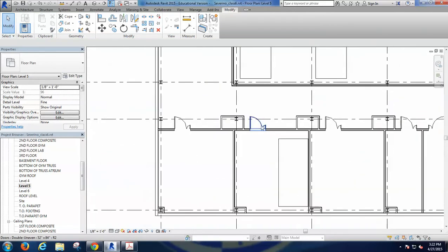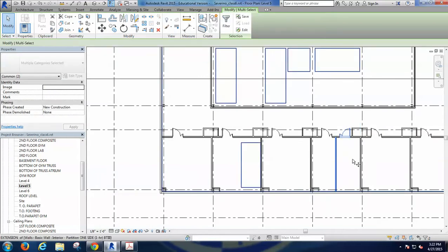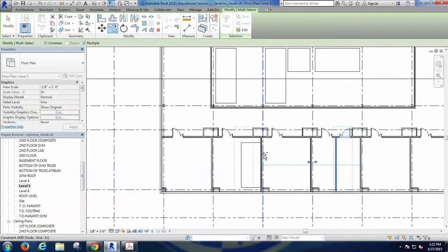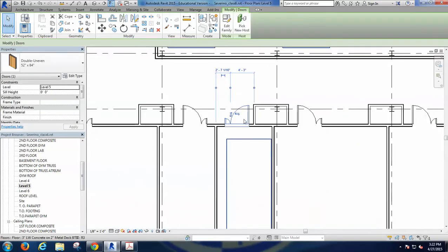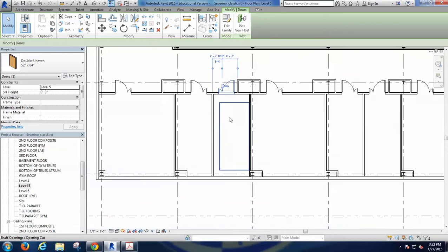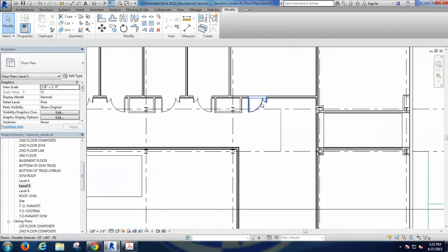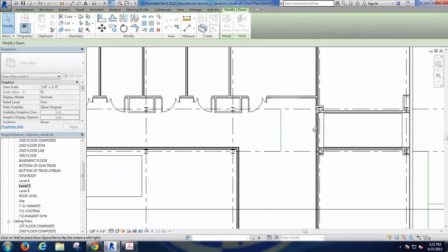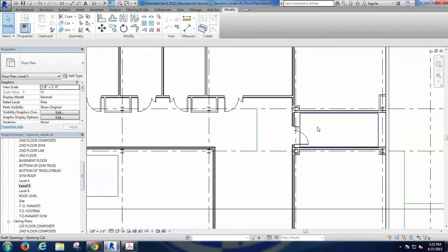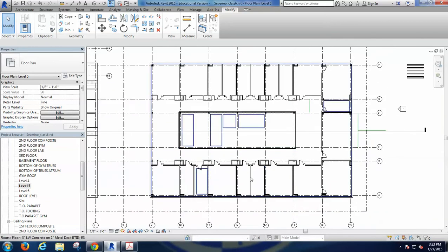And obviously here we're going to need some changes to accommodate the doors. So I could copy these elements from here, from the grid, placing it there. Remember that if we have a door opening to the evacuation stair, it should be opening always towards the inside. The same as here. You could again copy this one here, select the door, pick new host and place it there. So the door should be again opening towards the stair. So I'm saving that. It starts to have a layout quality.